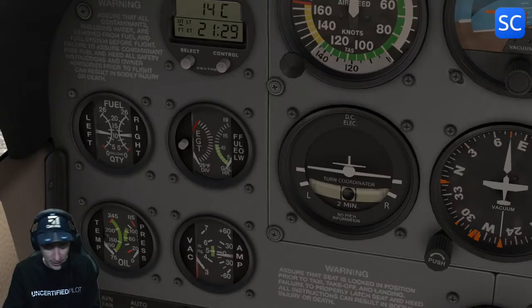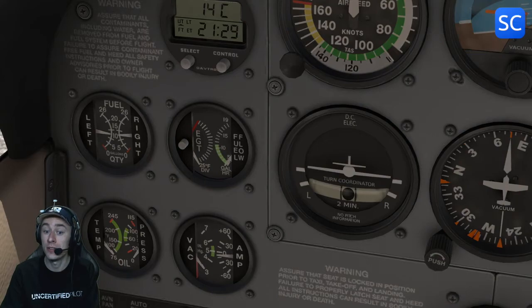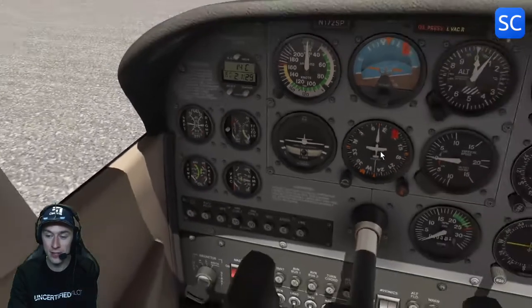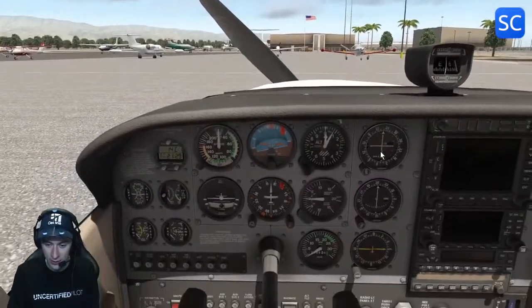So yeah, a little bit of throttle in, fuel pump switch on. There it is. Mixture full in. 1, 2, 3 seconds long. Cut off on the mixture and turn off the fuel pump. So now there's enough fuel there, hopefully in the engine, to start it up.